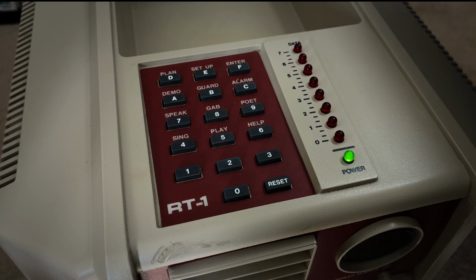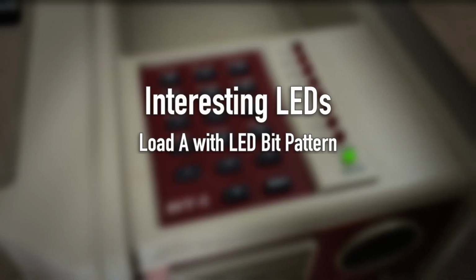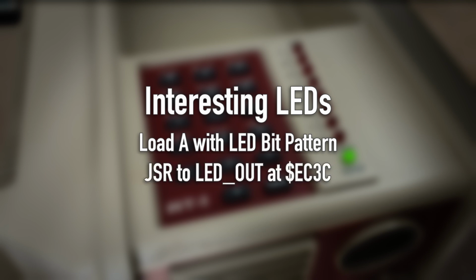Let's get fancier. Suppose we want to display something interesting on the LEDs. First, we would load an LED bit pattern into the A accumulator, and then JSR to the LED out routine at EC3C. Let's give it a try. But first, I need to explain what I mean by LED bit pattern.